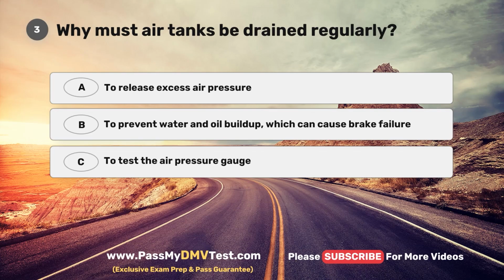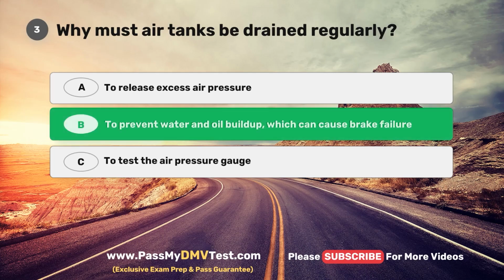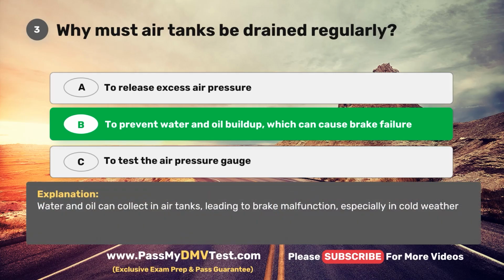Question 3. Why must air tanks be drained regularly? A. To release excess air pressure. B. To prevent water and oil buildup, which can cause brake failure. C. To test the air pressure gauge. The correct answer is B. To prevent water and oil buildup, which can cause brake failure. Water and oil can collect in air tanks, leading to brake malfunction, especially in cold weather.